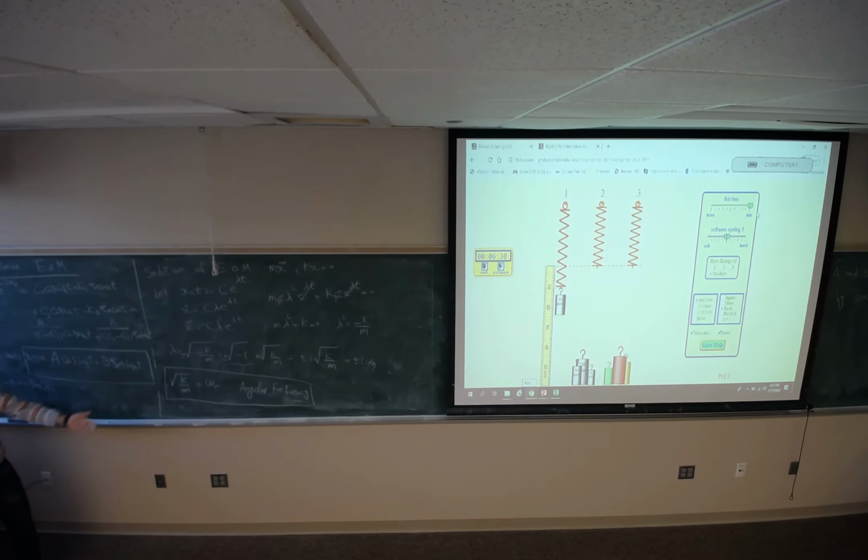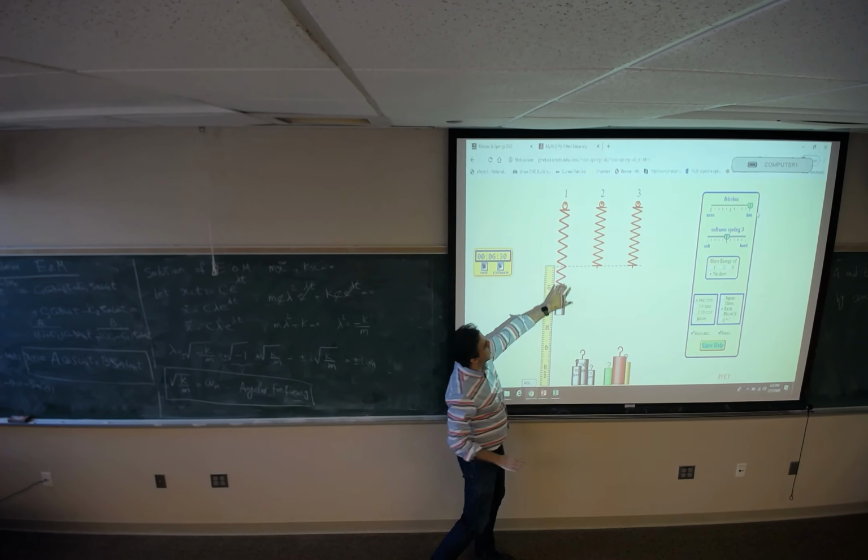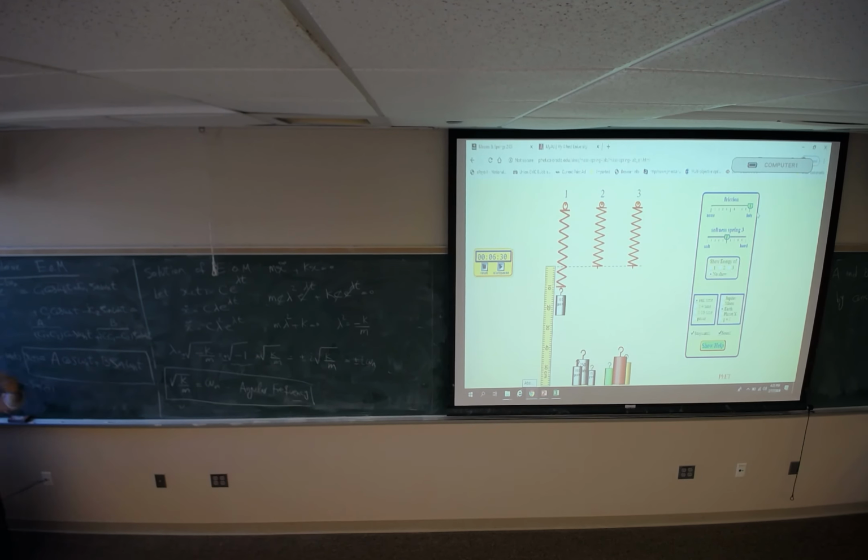So, mass spring system. The static deflection is 10. So when the motion just started, I removed this by 20 centimeters, and after I release that, it's going to start oscillation. So time 0 is going to be at this point. At time 0, what would be the value of x? It's going to be 20, true? So this is the initial condition. What would be the velocity? 0, it's not moving. So these are two initial conditions.